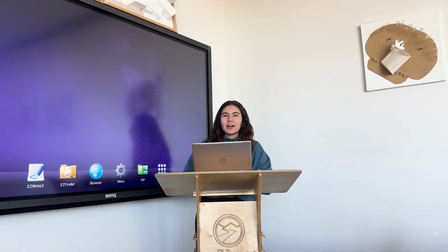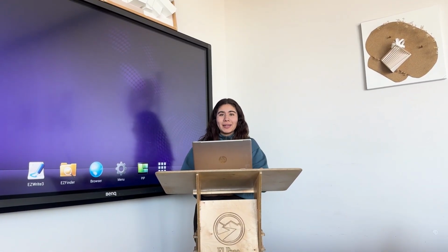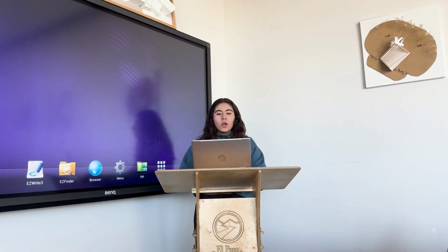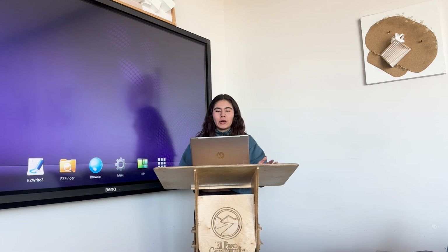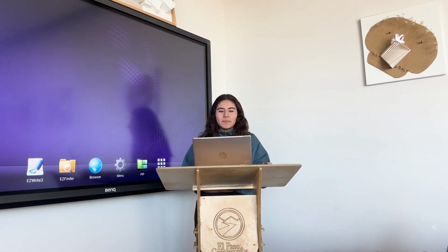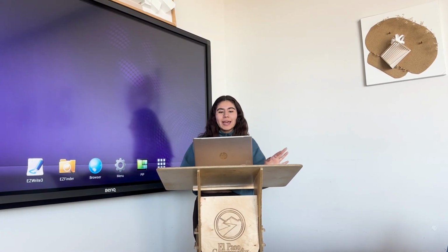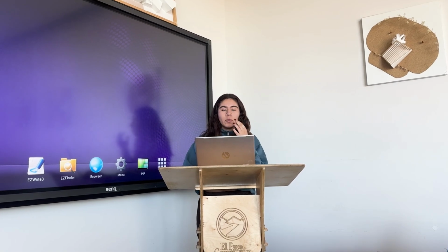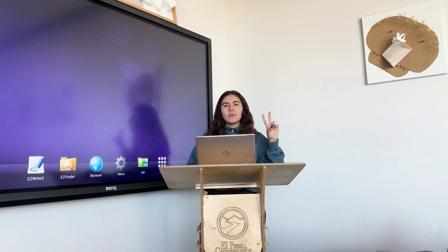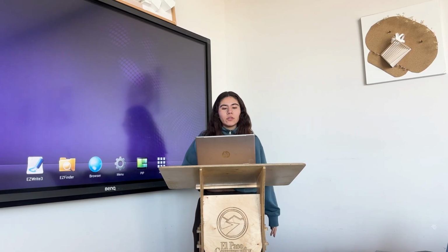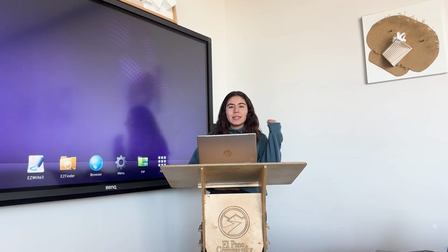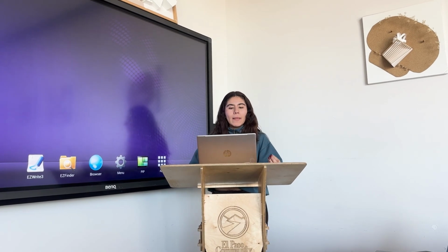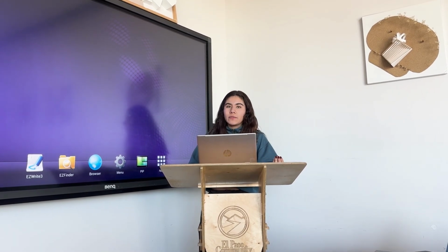Okay, I'm also going to be talking about special problems of masonry construction. So we have expansion and contraction. Masonry walls expand and contract slightly in response to changes in both the temperature and the moisture content. So the thermal movement is relatively easy to quantify. Moisture movement is more difficult.